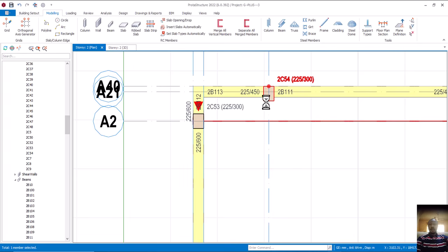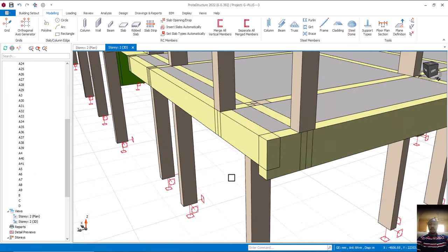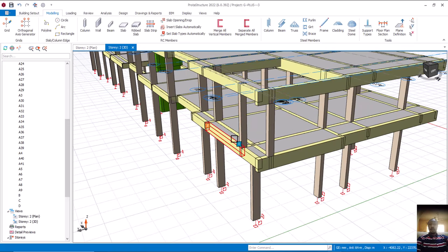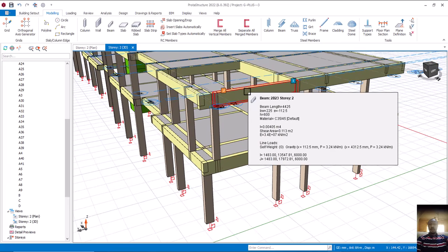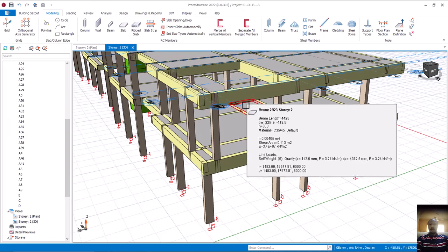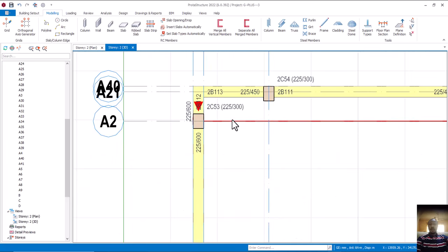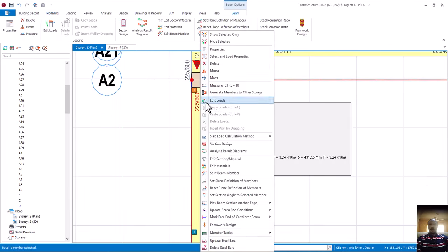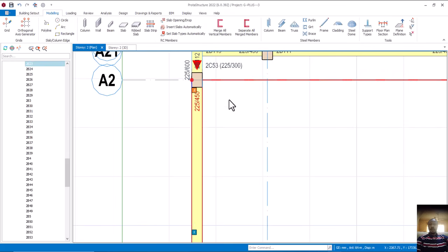Likewise, this particular beam, let's confirm this at the downside. Okay, we have adjusted this one. Let's see. Okay, there's a beam alongside here. Is that okay? There's a beam along this pattern here. Okay, this beam seems big. What do we have? Oh, 600. That's too much. So let's go and reduce it. Let's take it back. Is that okay? 600. Click on this, right click, and come to property, and turn this one to 450, then update. Okay, close it.